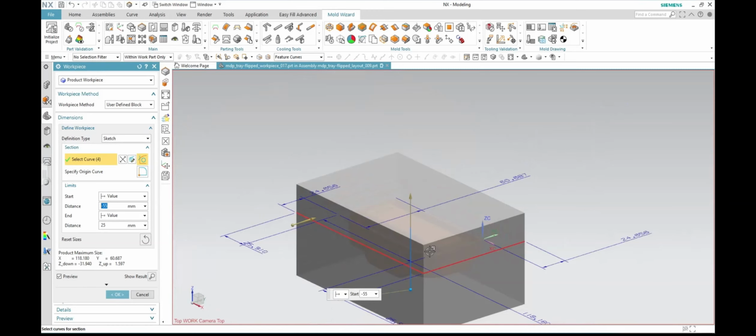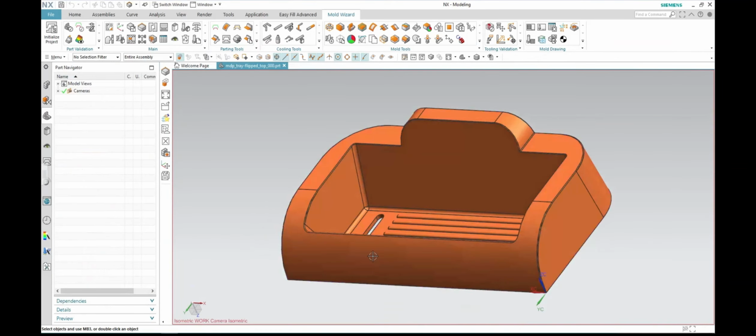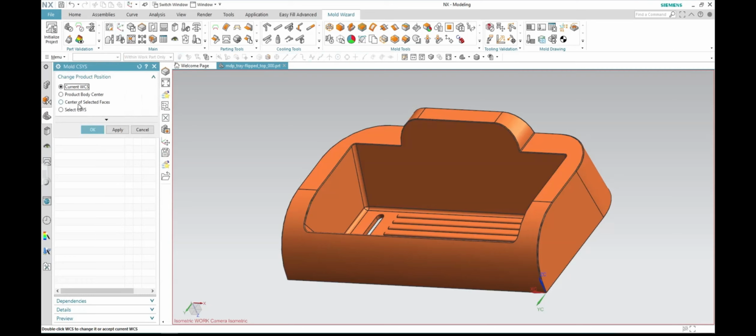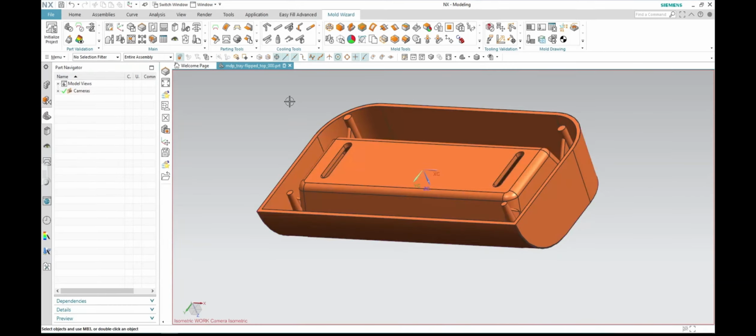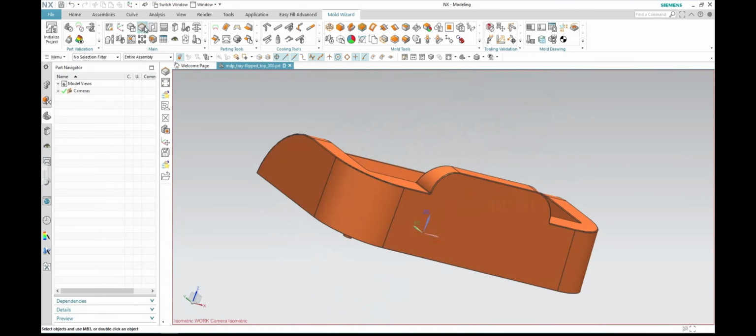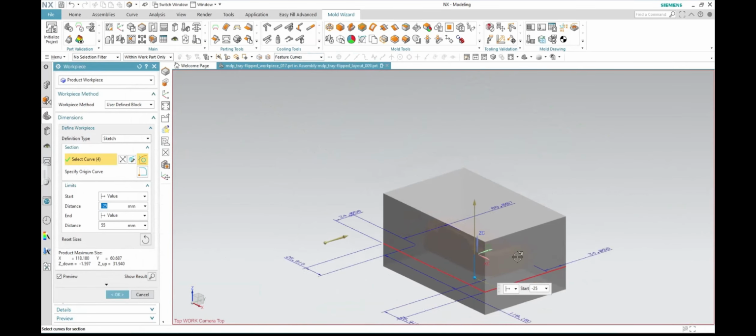The coordination system, if it's not in the middle, this is where you get the problem, which is why I said it's really important that while you're in the top part, you need to bring these basically to the center and make sure the Z is locked. I'm gonna put it in here. So, and now have a look at it. If I open it up, then this one goes in the center of that, and that's really important.